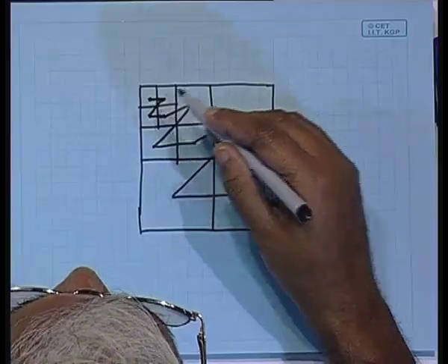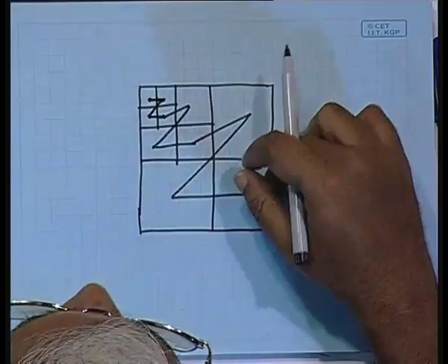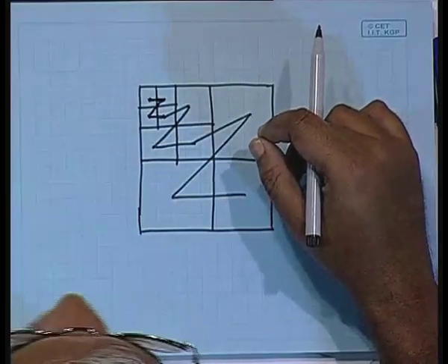As I was telling you, we will be finding that most of the coefficients are highly significant in the low frequency subbands. That means to say that in the LL we will be finding almost all the coefficients to be highly significant. And as we go on to finer and finer resolution, and that too in the high pass filtered subbands, we will be finding lesser and lesser significant coefficients. So, there is a possibility that we will be picking up a considerable number of insignificant coefficients or zeros when we traverse down this tree.